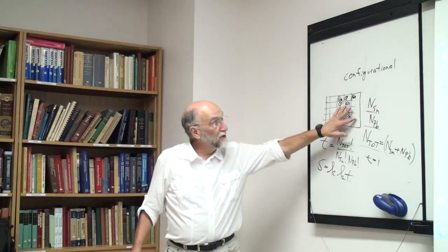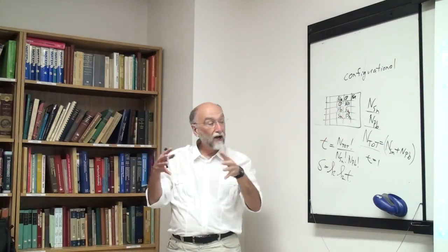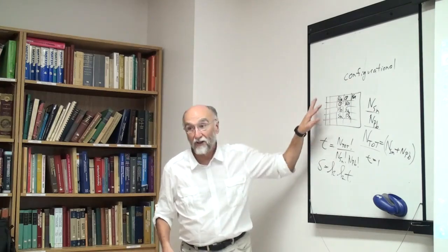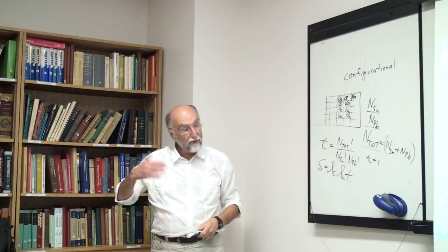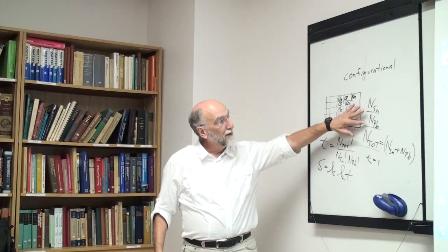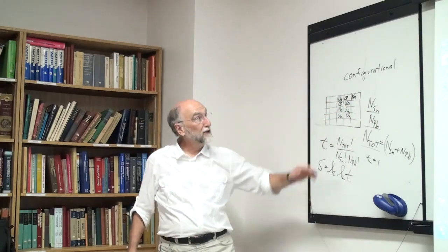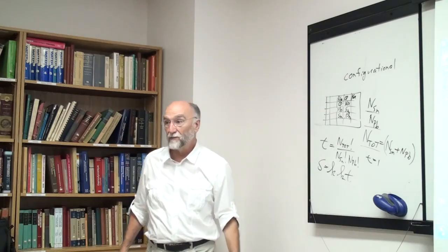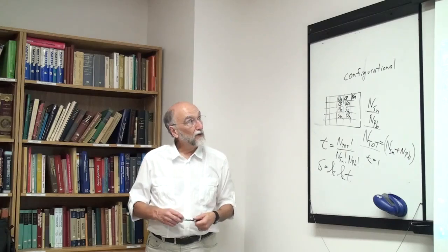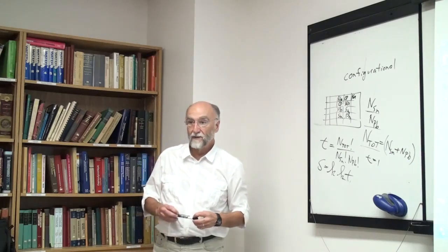In the lead tin solution, not only do you have the vibrational entropy due to the fact that it's not at 0 Kelvin, but you have the additional configurational entropy. So the entropy is the sum of the vibrational entropy plus the configurational entropy. In sodium chloride, it's all vibrational entropy. I'm doing this just generally now. We'll go back to this more exactly in the future.